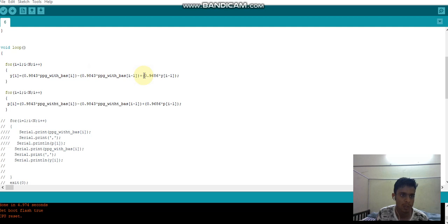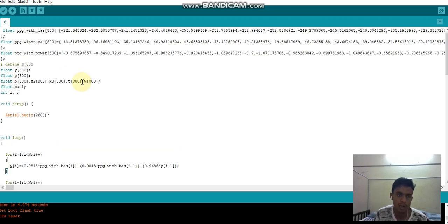For designing the notch filter, we first have to calculate the radius r and find the gain. Then, using those conditions and formulas, we get the difference equation of the notch filter. We will pass the PPG signal through this notch filter to remove our power line component.